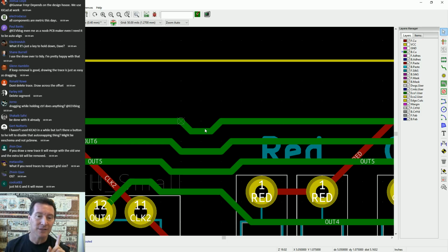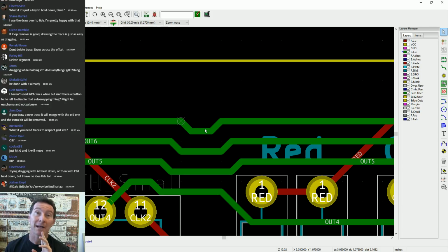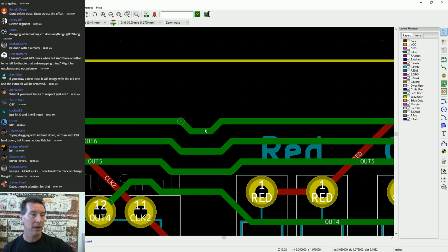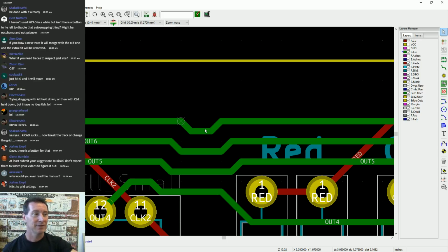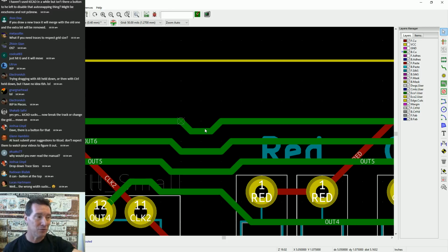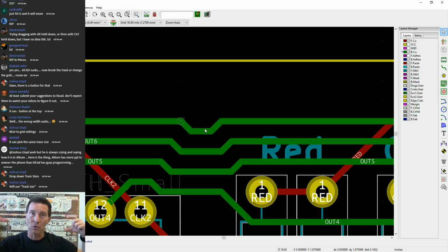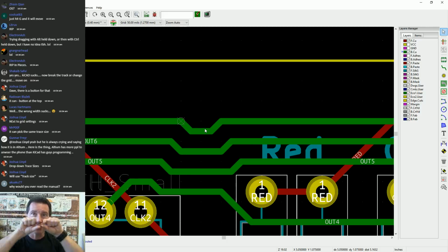Okay, I'll ask this. Does KiCAD have the ability to automatically pick the existing trace size from the trace I connected to? See, a professional tool would at least give me the option to automatically pick the trace size and overrule the current trace size to the track that I'm editing, right? Because generally you do not want to neck that down, which is what it's called. That's the industry term for when you go to a thin trace.